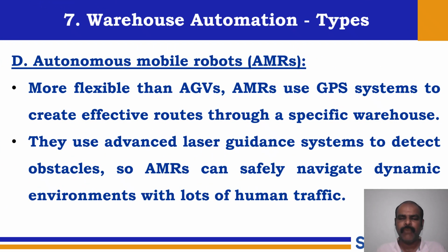Now, the next, the fourth one, autonomous mobile robots. Earlier we saw the AGV, automatic guided vehicle, which has a track guided by the user, maybe a magnetic strip, a wire, or paint. Even paint is applicable. And it is only applicable for large cases. For small cases, it cannot handle the turning radius in an appreciable way. The other thing is frequent disruption by human movement. Again, it is not recommended.